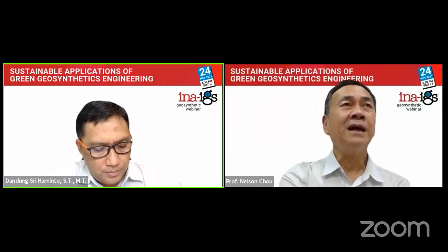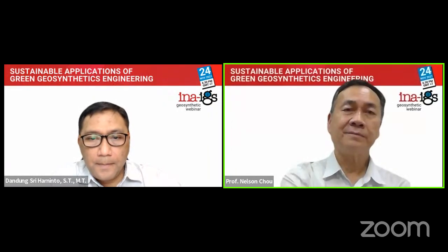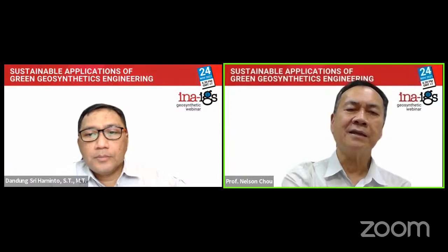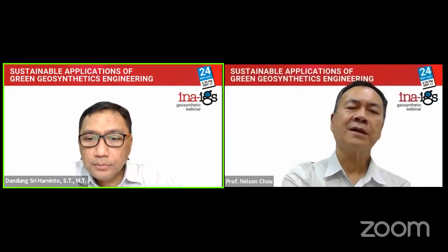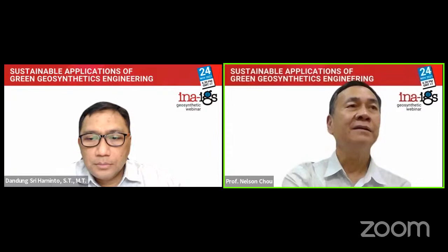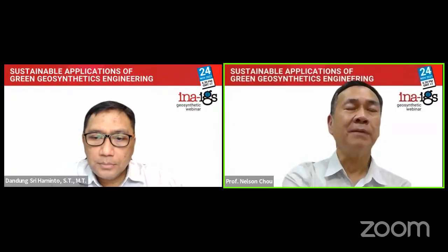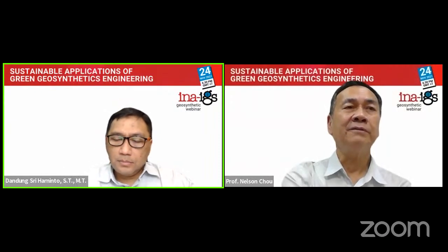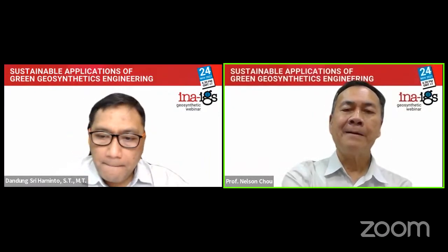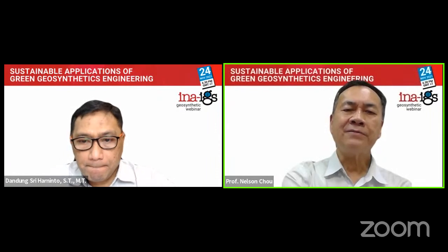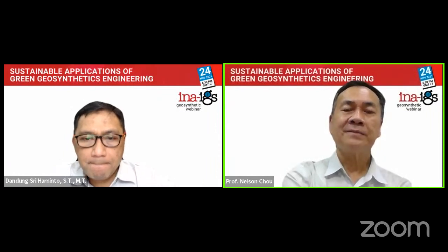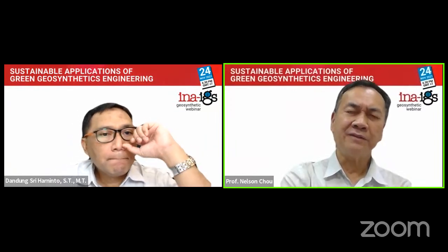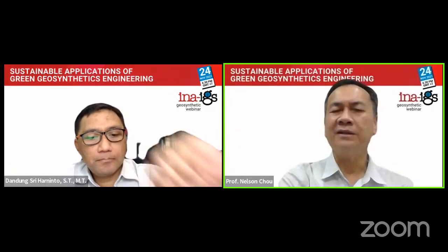It may be a little bit higher in initial cost because they're made of concrete, also made of geosynthetic frame and the tube. The cost is a little bit higher than the conventional pervious pavement, either it's pervious asphalt or pervious concrete. However, it can last for many years. You don't need a resurface. You don't need to get rid of the surface and resurface and so on.